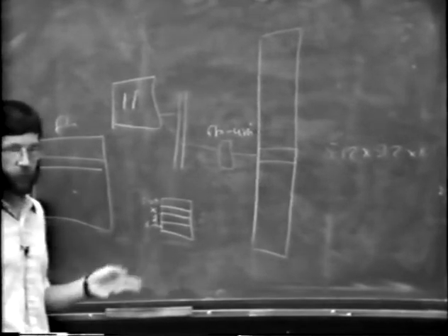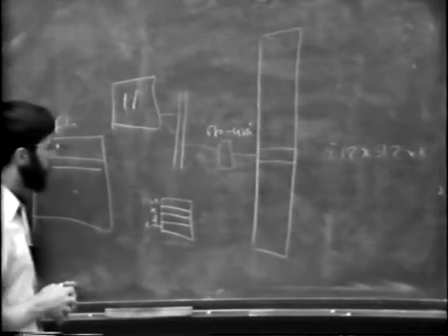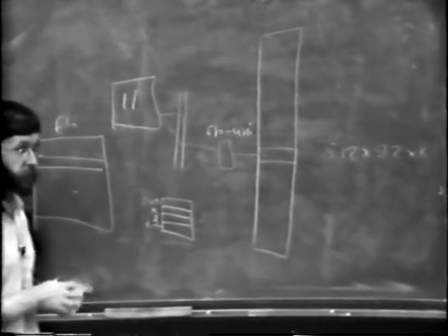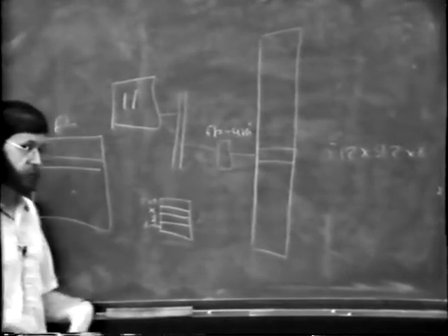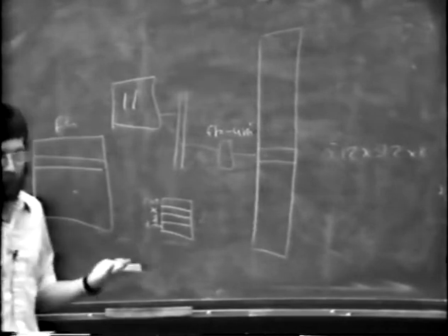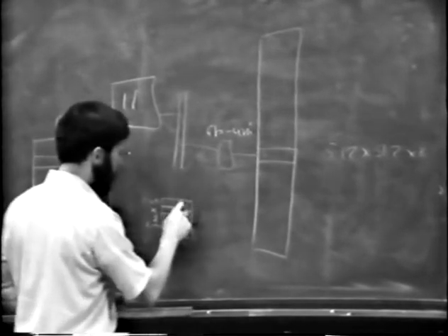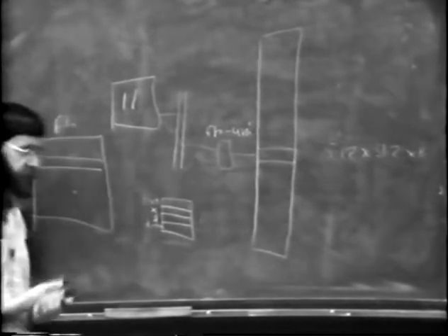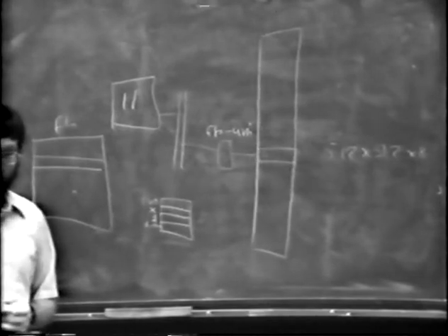You can do arithmetic on it. Anything you could do to any other memory location on the PDP-11. And if you were doing wholesale transfers, you wanted to move things around quickly, you'd take a word at a time. The purpose of the status was to make it so that if you have this bit set, whenever you did an access, X was automatically incremented or decremented.